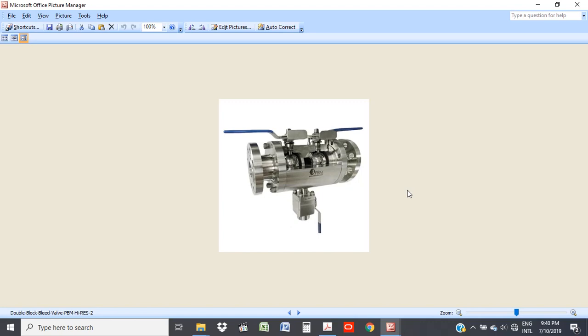This is very necessary because sometimes when you want to work on an equipment and you close a valve to isolate it, and then you go to the equipment and start work there, maybe try to open up the flanges, you'd notice a hiss of high pressure, meaning it has not been depressurized. That could be very dangerous because high pressure gas coming out with you there could lead to a hazardous scenario, either fires or you being exposed to high pressure. So you don't want that. You want to positively isolate before you start work.